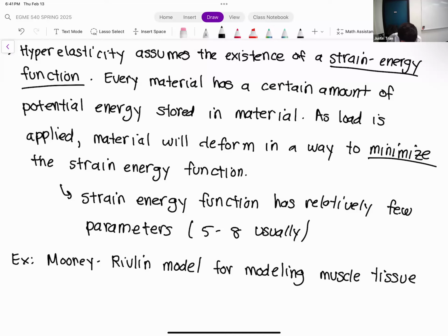So muscle tissue is really interesting because it's a material that people often describe as viscoelastic. And so it has properties of a fluid, but also properties of a solid as well. And those have been notoriously difficult for, let's say, structural mechanics to really model their behavior, just because the fluid part kind of goes. But with a hyperelastic material, it's very easy to define that material behavior over the different regimes. And this one in particular, the Mooney-Rivlin model, works particularly well for it.